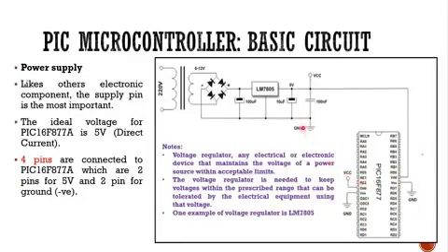First, we will look at the assembly of the supply circuit to the PIC. If you want to connect the PIC microcontroller to an AC power source, especially the grid, the system starts at around 220 V AC. From here we drop the value from 220 to around 6 to 12 volt, still AC.